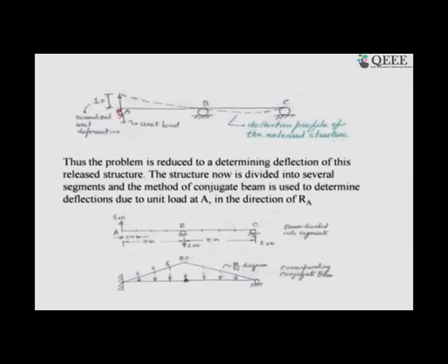You see that I have released the redundant, then I have put back a unit load here. So, you can see this will go up, as if you are doing an experiment. And one confusion the students may have concerns the roller joint and the pin joint. It appears sometimes to the student's mind that it is as if you are putting a particular beam over a drum type of thing, so it can well be taken up.